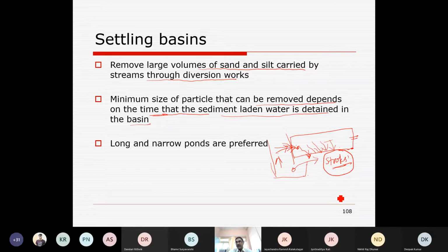If you recall, in your second year you might have learned to find out the sand, silt, clay content of the soil, that is textural analysis, by putting soil in a jar, say 1 liter, of certain depth. If we mix the soil well with the water and sample at a particular depth, generally 10 centimeter, the first sample gives us silt and clay content. After say 24 hours, if we sample, it will give only the clay content which is suspended. And sand particles are settled down immediately, within the first 10 minutes.